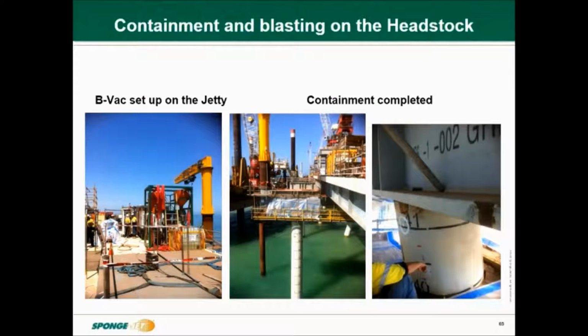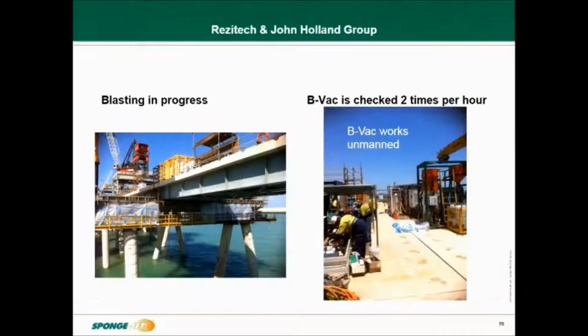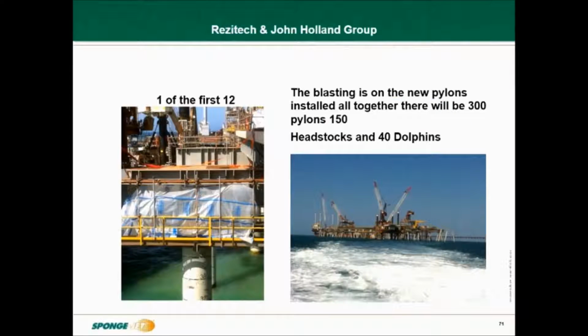Once a habitat had been constructed, all the blasting and coating requirements can be performed inside the same habitat. There's no need to remove and rebuild it for a coating process. A picture is a good message. If they can see what the setup is like, then there's no reason why they can't duplicate the process. With 4 kilometres of loading wharf to build, paint and blast, it's quite a sizable project to compare it to a bridge.